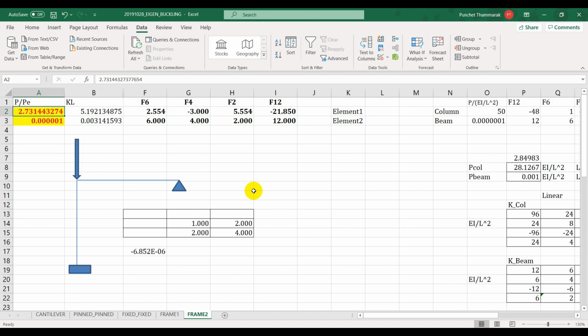you might have distributed load, or maybe the load applied on the span. So first of all, you don't know how much load comes to each column, right? Because you have not done structural analysis. But you have to do structural analysis. But you don't have the P information. So we will start from the guess value of P. Once we finish the first round of analysis, you'll be able to determine the axial load distribution in all columns.